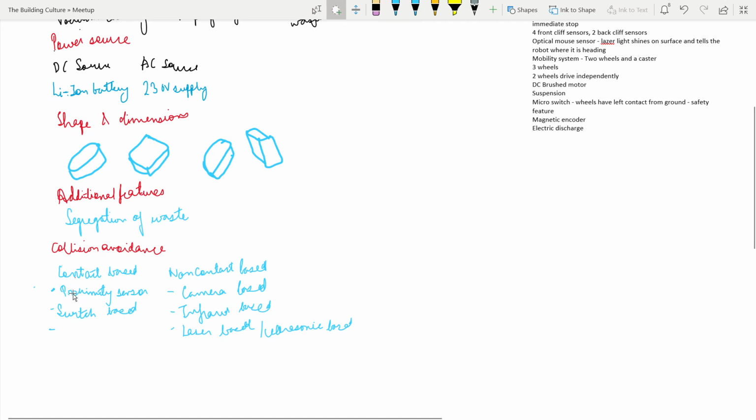So actually I've written it in the wrong place here then. No, this is correct. This is what is used behind the bumper. But then it's not in contact based, right? Yeah, that's what I'm telling. Our goal here should be written that you should have a physical bumping mechanism. So it's touching something. That is the concept. Okay. Behind how you use it, that's where you come with button based, proximity based. What is important is there should be a contact surface. The robot should have a contact point where it should touch and feel.